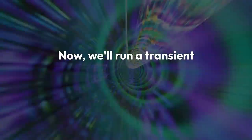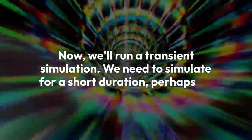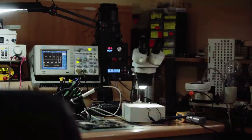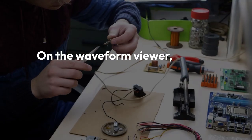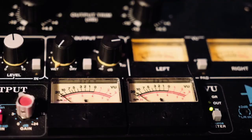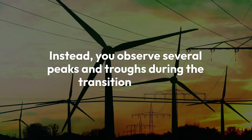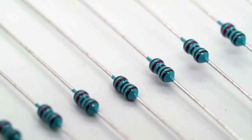Now, we'll run a transient simulation. We need to simulate for a short duration, perhaps 20 or 50 milliseconds, to clearly capture the bounce event. Once the simulation runs, we will probe the output node. On the waveform viewer, you will clearly see the voltage rapidly fluctuating up and down. It won't be a clean, sharp drop from high to low. Instead, you'll observe several peaks and troughs during the transition period. These represent the mechanical bouncing of the button contacts.